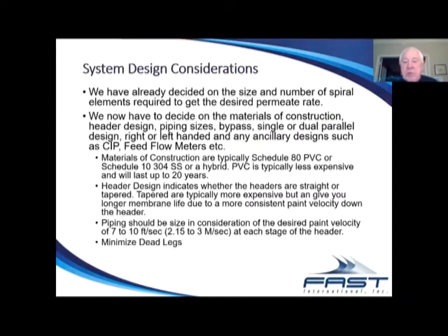But typically we use either Schedule 80 PVC or a Schedule 10 304 stainless steel, or sometimes a hybrid, where the headers are stainless steel and the housing bodies are PVC, and the permeate lines are PVC. Typically PVC is slightly less expensive than stainless steel. It will last up to 20 years. But for all of you that might have 20-year-old systems, that PVC is getting very brittle, and you could have problems with it.